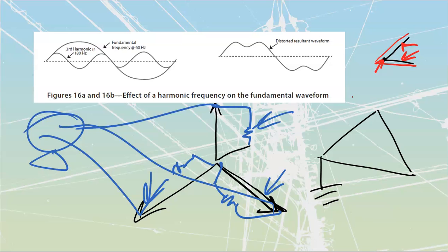Phase currents. We can imbalance the voltage through accidental grounds or through single phase loads as well. If I imbalance my loads, I'm also going to get that imbalance of currents. Basically the same thing, so we're not going to talk much about the phase current imbalance other than where we sometimes get these things from.